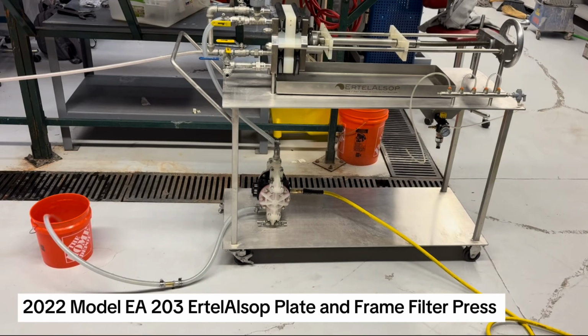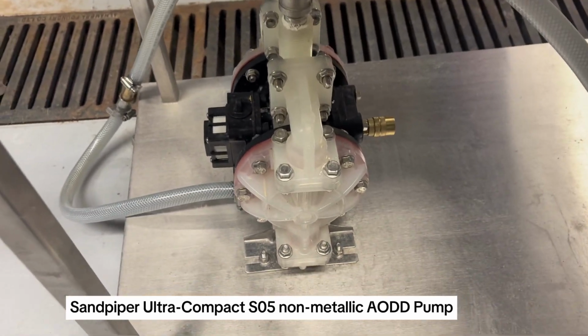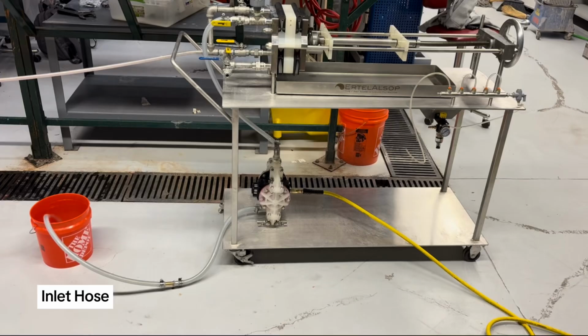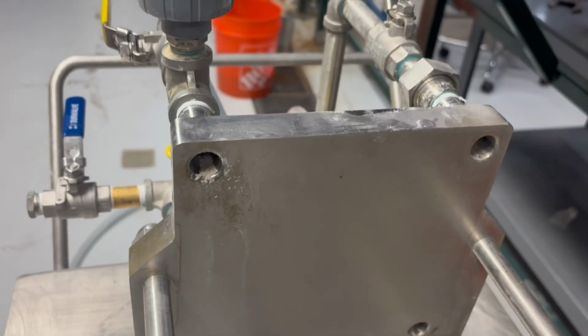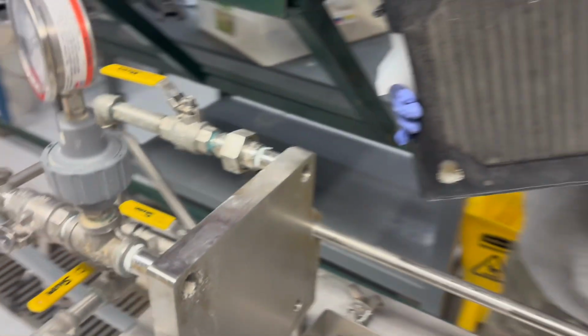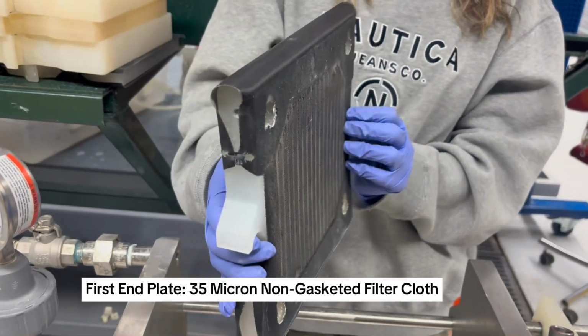This is a plate and frame filter press donated to the University of Nevada, Reno from Lithium America. Slurry is sent through the filter press by a Sandpiper diaphragm pump. From the inlet hose, the diaphragm pump sends slurry into the filter press inlet. From there, the slurry passes through the first end plate, fitted with a 35 micron non-gasketed filter cloth.